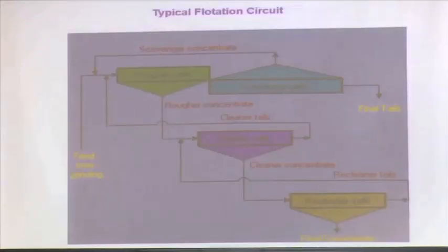Now, that is why, if I have a complexity of materials like that, we try to separate. Suppose we have decided that we have to go for a flotation cell. In a rougher, normally we target, there is no clear-cut rule, it depends on the ore characteristic. I may first try to separate out my unwanted material like silicates, like in lead zinc ores. I have unwanted material as silicate, I do not see any value in that. So, I will first try to discard my unwanted materials.